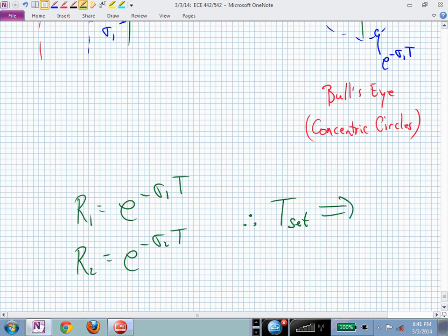What should come to mind? Your ABCs, and you need to get all the way up to R, don't you? You need to say, oh, settling time, R. I need to worry about being a certain radius away from the origin in the z-plane. If somebody gives you a settling time spec, you think radius in the z-plane.